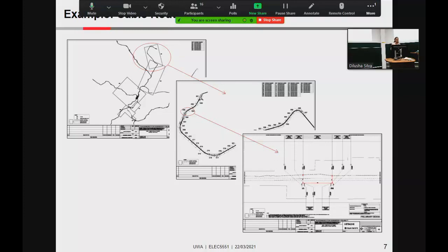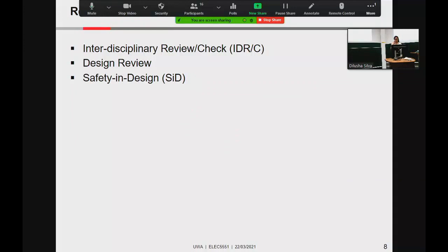So this is the kind of detail we put in. Further down, these little boxes are the cabinets. The cabinet layout, then inside the cabinet, you can have a cabinet elevation, which shows which equipment goes at which level, and then if the equipment has sub-boards or modules, that layout. So this is the example of preliminary layout.